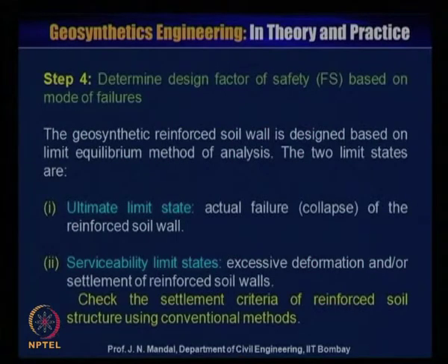Now step 4, determine the design factor of safety based on mode of failure. The geosynthetics reinforced soil wall is designed based on the limit equilibrium method of analysis.